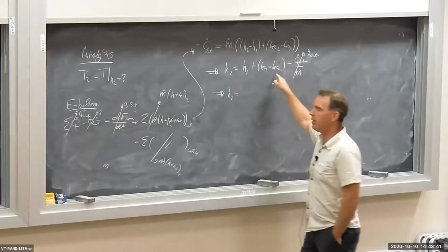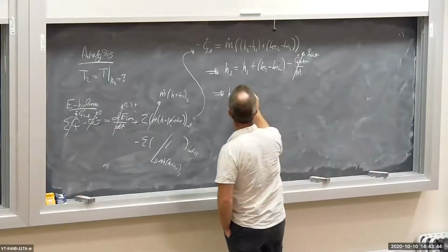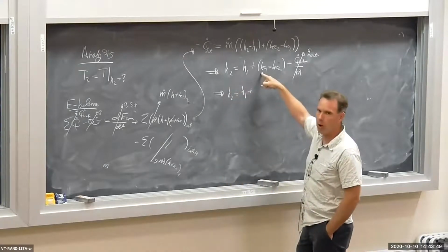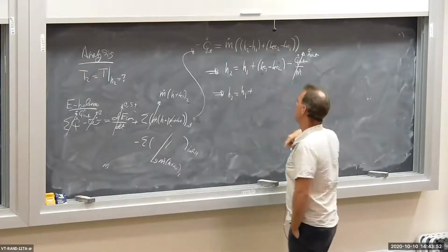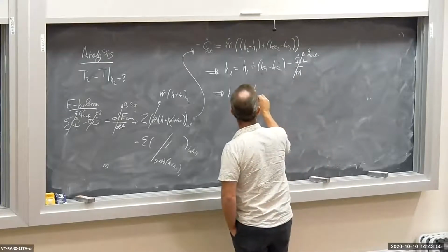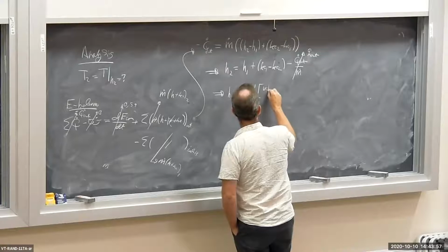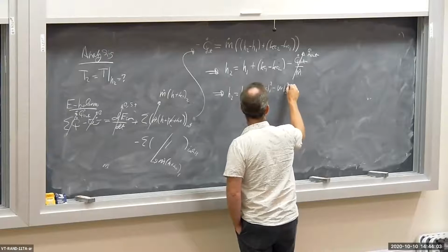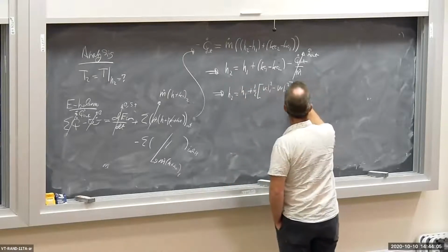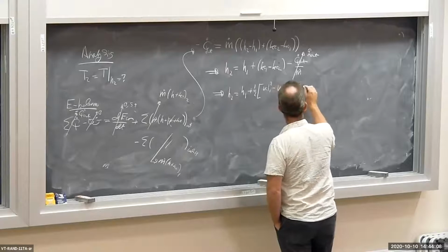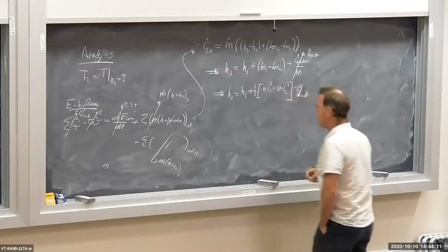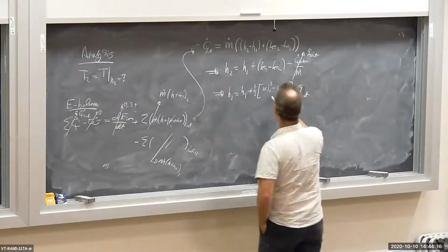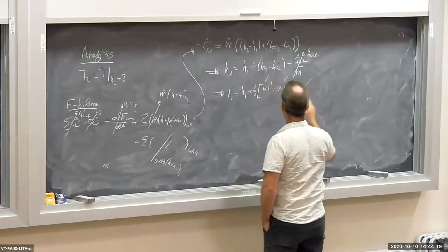So my final equation here, we have H2. Let me expand what these kinetic energy terms are, specific kinetic energy. So I have H1 plus, and each of these is going to be one half velocity squared, so I'm going to factor out the one half. I have velocity at the inlet minus velocity at the outlet, both squared, and then I have negative Q out. Now, I know these velocities, velocity 1 and 2. I know the heat transfer out.